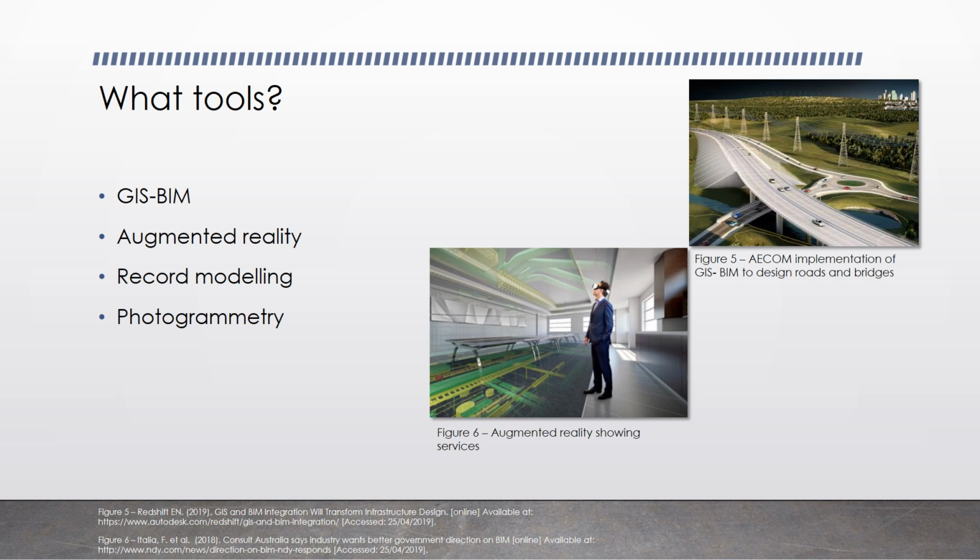Record modelling. This allows accumulated information such as the configuration and assembly of components of construction using precise dimensions. This technique is useful for the construction teams to prepare detailed specifications to be handed over to the maintenance teams in the occupancy phase. Photogrammetry. This allows measurements to be taken from photographs taken on site, which then can be contributed to the updated detailed BIM model. This is especially useful for the project management in identifying issues with construction and the best ways to proceed in the project.